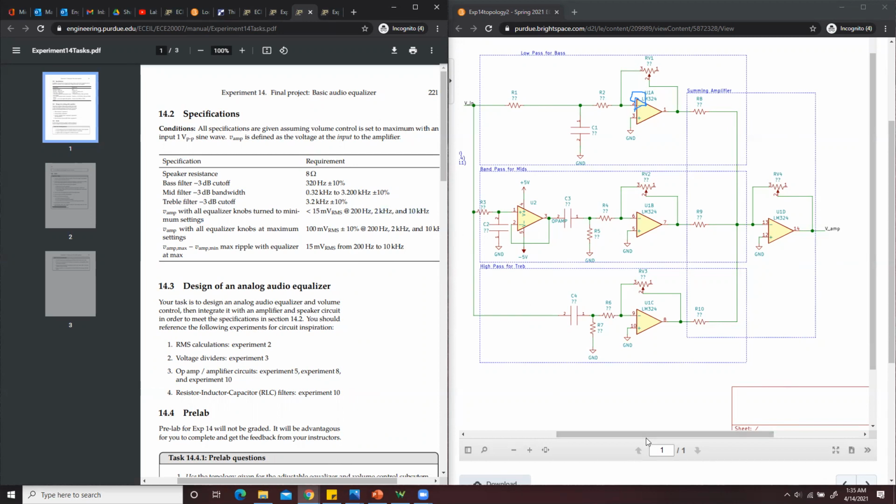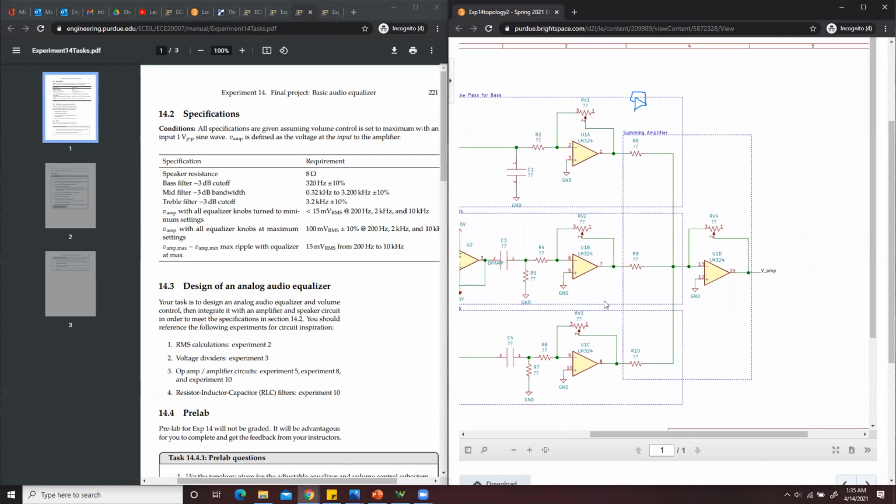So basically, what you will see is after you build this circuit, the signal will be something like this. First of all, the low pass filter, the signal is something like this. So this is a magnitude response when you use the network analyzer from the AD2. Then this is a high pass filter, so the magnitude response will be something like this.